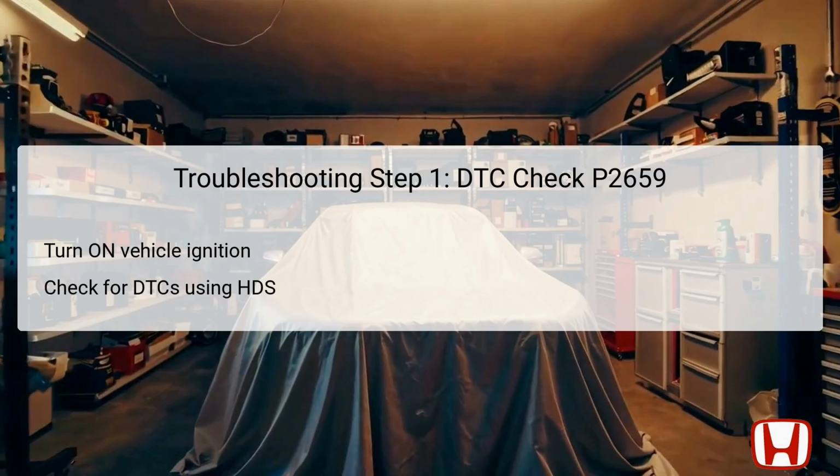It's crucial to look specifically for DTC P2659, along with any other related codes that may indicate simultaneous issues in the engine control module. Identifying whether codes like P0102 and P2649 are present is key, as the diagnostic process may differ based on their presence. The HDS provides valuable data that helps pinpoint the source of the problem and guides further troubleshooting steps effectively.